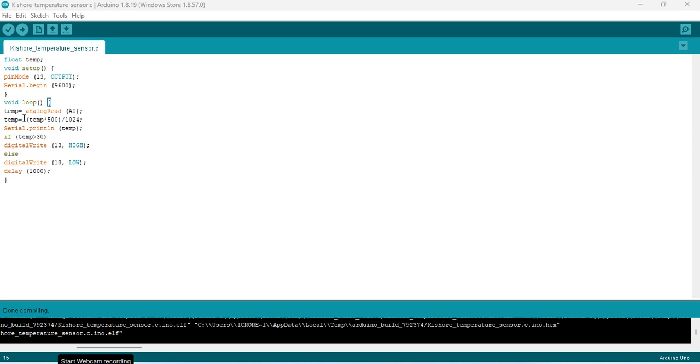From the input voltage, the value will vary up to 1024, so it will divide it into 1024 steps. This is the formula for the conversion, which will convert the analog value of the temperature into digital format, because almost all the display technology we use today is digital, mostly digital electronic devices. So we only want to convert it from analog to digital.